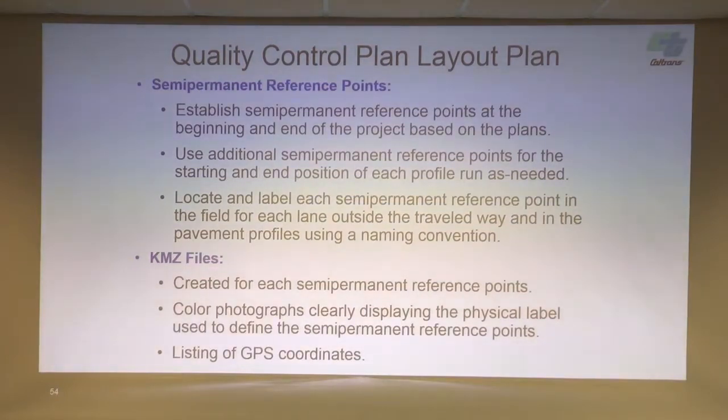Okay, so the quality control plan layout. The semi-permanent reference points. I talked about this layout plan earlier. These semi-permanent reference points are really important. We're going to establish a semi-permanent reference point at the beginning and the ending of the project, and it's based on the plans.